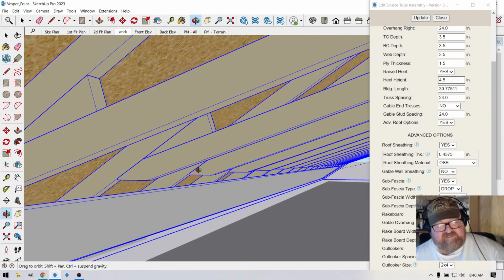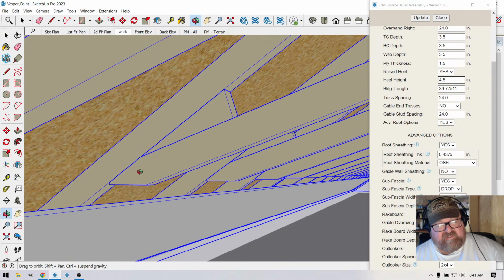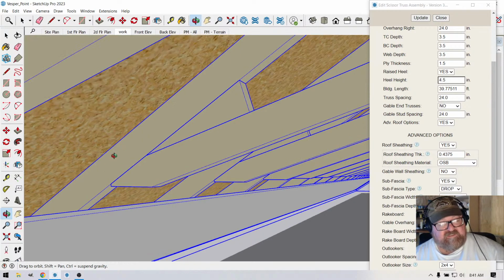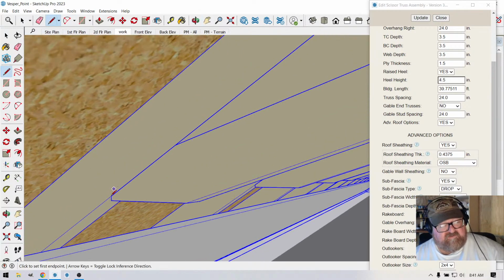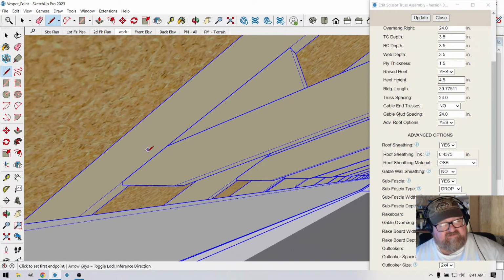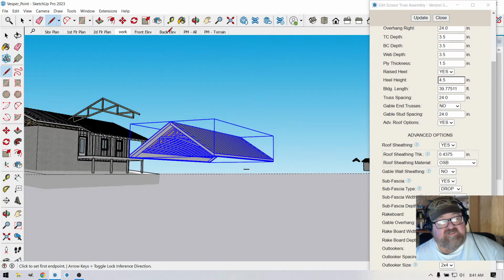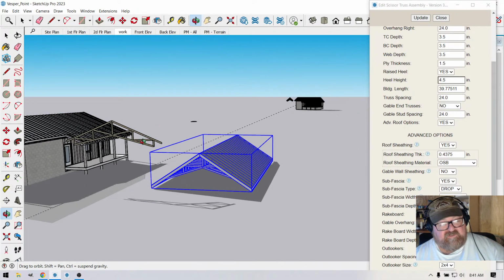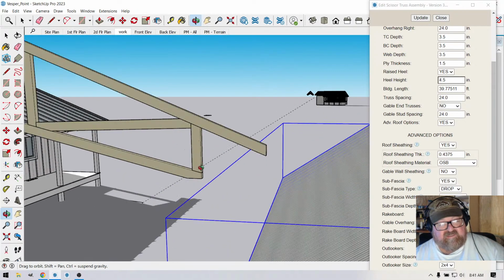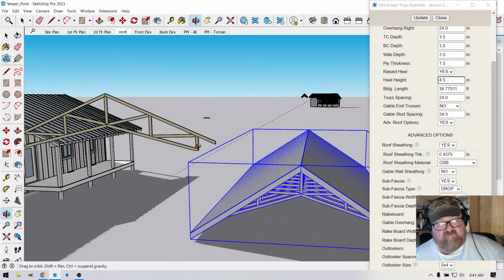and really the scissor truss isn't a good example of this, but in any event, your bottom chord would come over, and here this is where it sits on the wall, and the heel height is this point right here. It's how tall your truss is from here to there. A typical one is about 4.5, 5 inches, right? It's just where the top chord comes right over the bottom chord, and it's the minimum thickness that you need to do that with.